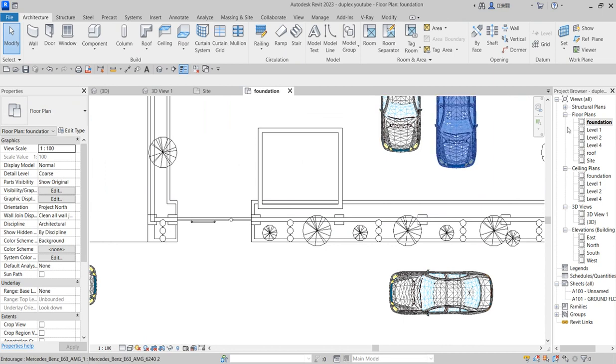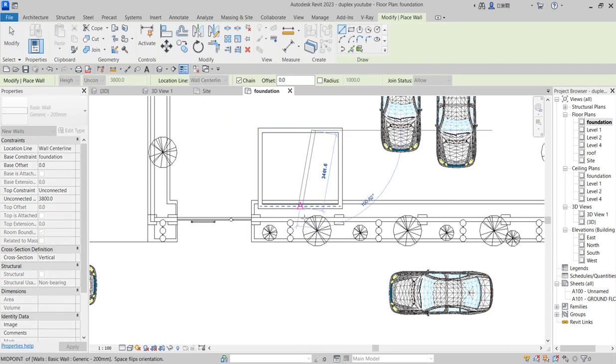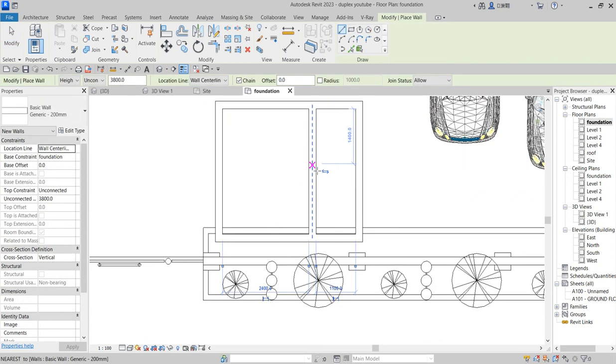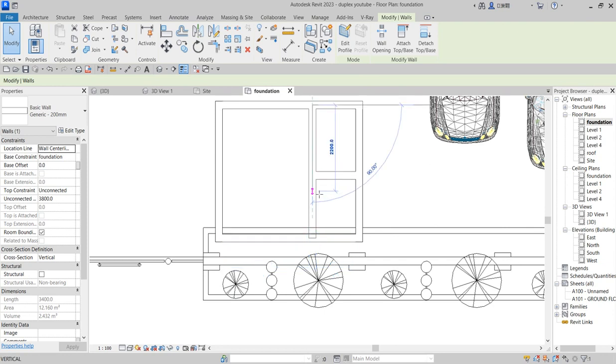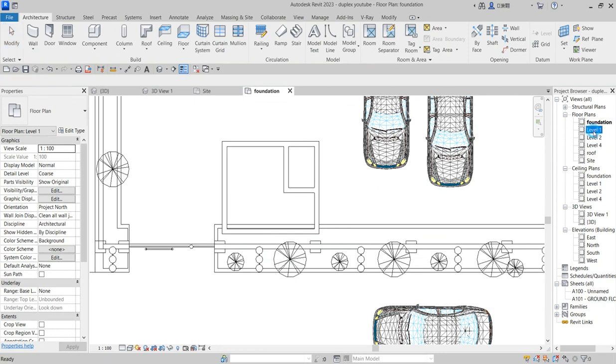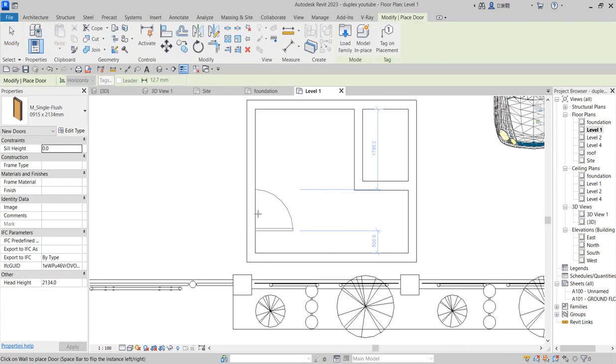So as you have done this one, you can decide to continue editing it by creating toilets and maybe a mini kitchen. You can have it like a studio. So what we do is that you open this up, so the kitchen is going to be an open one. So go to level 1. At level 1 you can now introduce a door. Click on the door and bring the door inside.